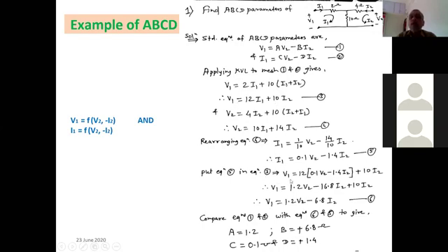So that you will get V1 is equal to 12 into this I1 value, which is from equation number 5 that I have substituted, plus 10 times I2. Okay. Then simplify this equation, club all the terms of V2 together, I2 together and V1 together, and keep V1 on one side and V2 and minus I2 on the other side. Okay. So after rearranging this, we'll get V1 is equal to 1.2 V2 minus 6.8 I2. Let us say this is equation number 6.